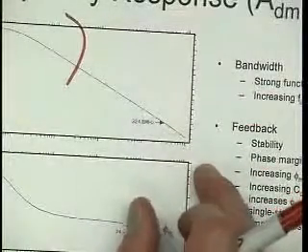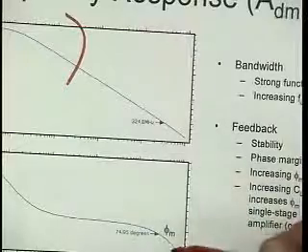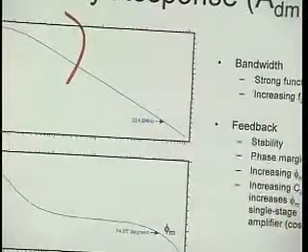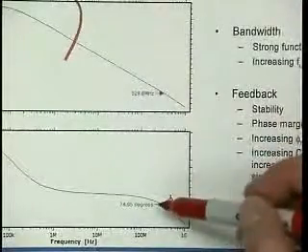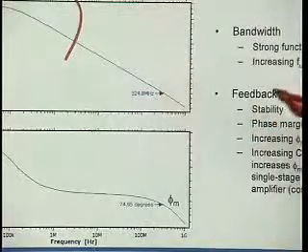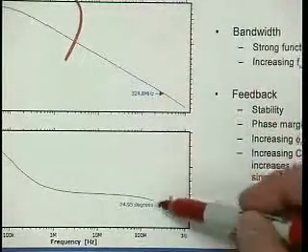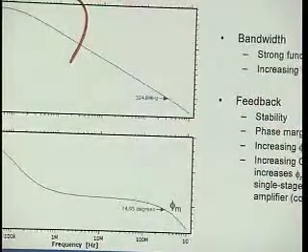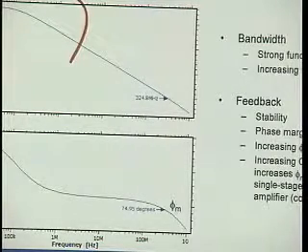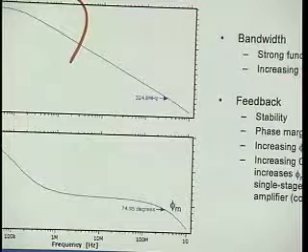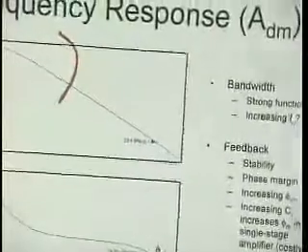We know now that's the cascode, right? And because of that, we get the finite phase margin. Now that's interesting, right? This unity gain frequency, 300 some megahertz, and the phase margin here 75 degrees, not too bad, right? Now you can design it again with NMOS inputs, and you may well end up with 65 or something like that.